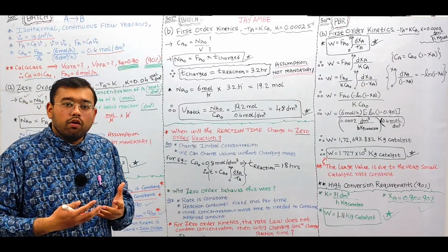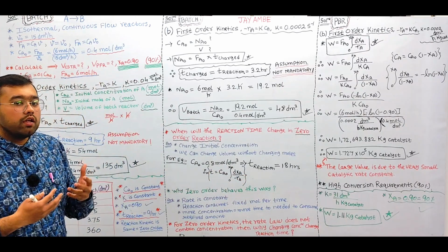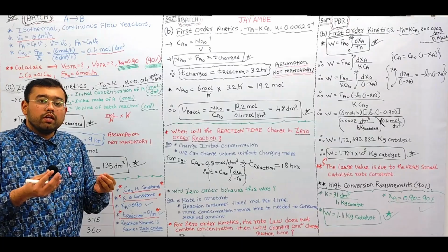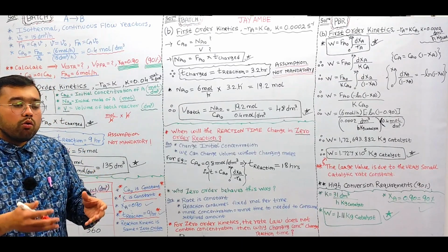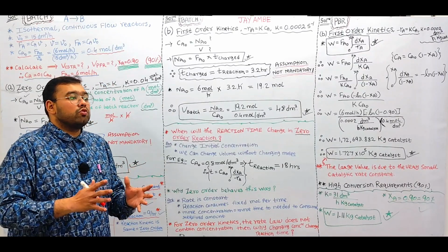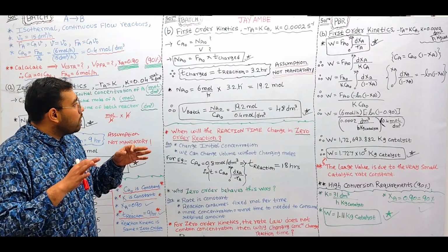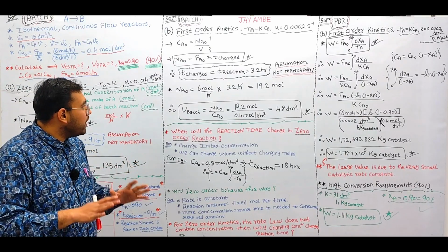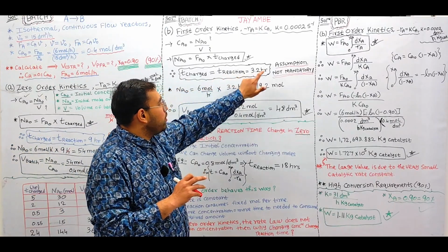of the batch, a large volume of the feed, to the batch reactor within a few minutes or hours, right? If we have lower pump capacity, it will take a very huge time to fill the entire volume of the batch reactor, right? So for current understanding purpose, I'm assuming the charge time is equivalent to the reaction time of 3.2 hours,